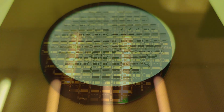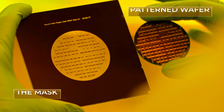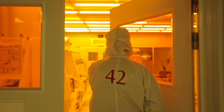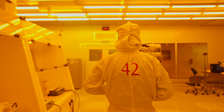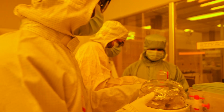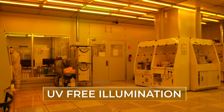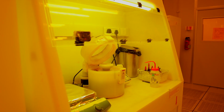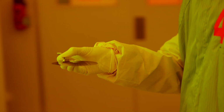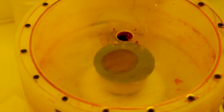It is now time to transfer the pattern that is there on the mask plate onto the wafer surface. To do so, we will now travel from the chemical vapor deposition reactor to the lithography bay. Lithography means writing with light. You will see that the bay here is flooded in yellow light. It is ultraviolet, UV-free illumination. We will first spin coat a special chemical called a photoresist or PR on the wafer. It is special because it's chemically altered by UV light.